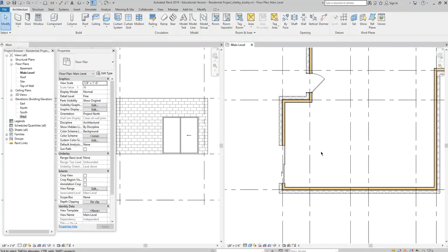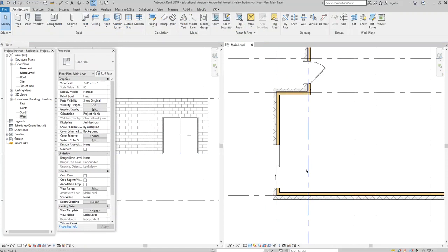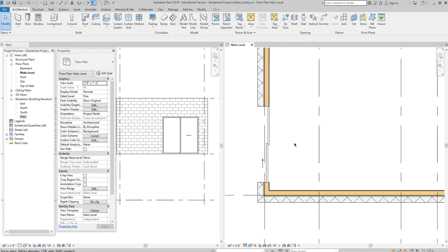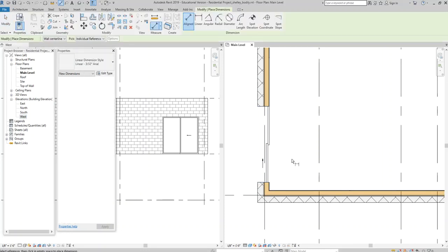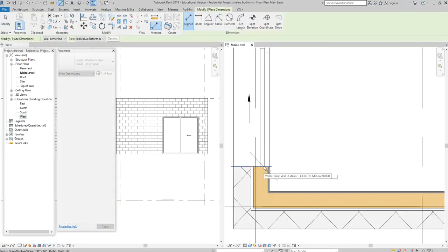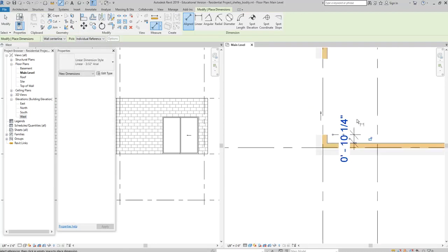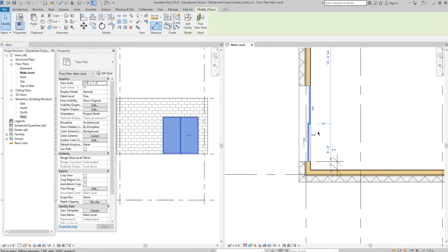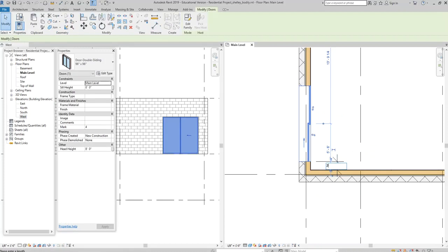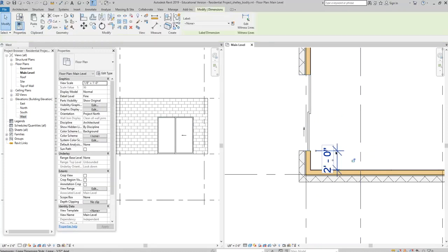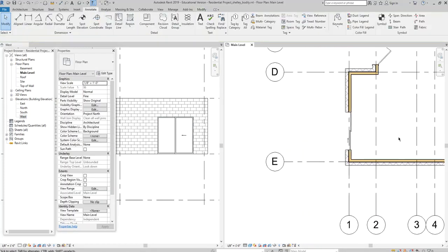Now I just need to position it wherever it ends up needing to be positioned. So I'm going to use my little dimension, annotate, aligned, click, tab, click, and maybe I want it to be 2 feet off of that wall, 2 foot, enter, click, delete. There we go.